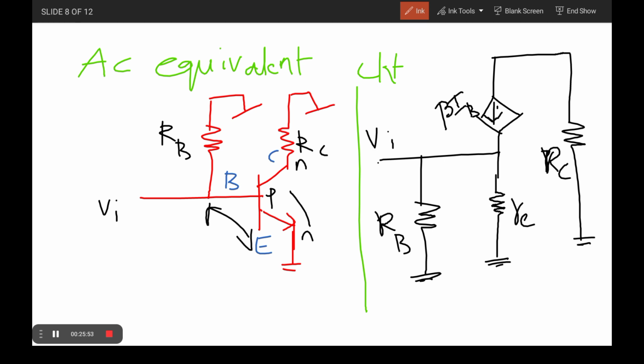So that's why, in the case of the AC signal, there is no drop, because it passes through the slope, both positive and negative. That's why no drop takes place. But the drop takes place only for DC signals. That is also a very, very important point. So that is all about the transistor re model, or small signal model.